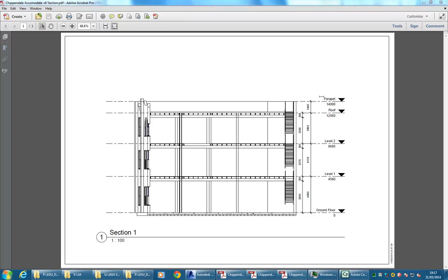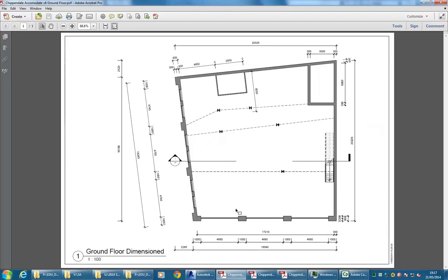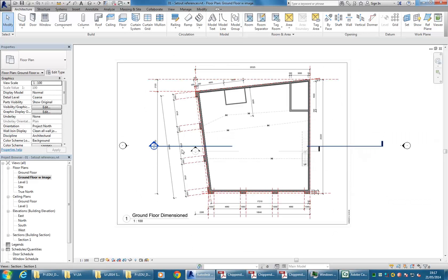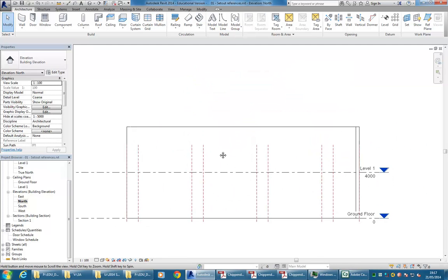But also, if you have a wall above that or any other major feature that's above the height of your roof, then it's also a good idea to have a level for that. And parapets will be the most common, where you need a level that's above your main roof height. So here I'm going to need an extra 3 levels, and going into Revit, that's really all you need to know initially.